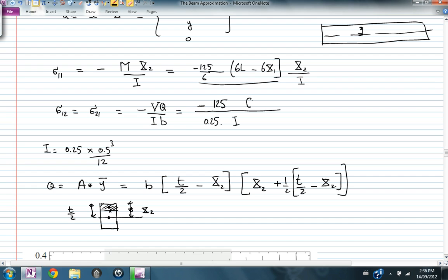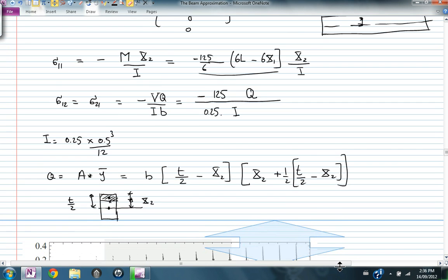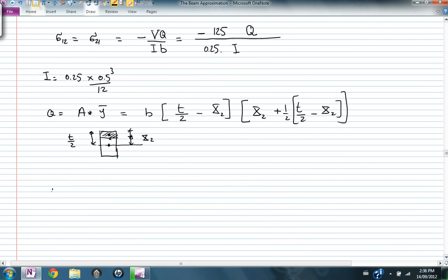And so you put Q here, and this gives you sigma 1, 2. So your stress at any point inside the beam is given by a matrix, because the stress, as we know, is a matrix of values, where you have a value of sigma 1, 1, you have a value for sigma 1, 2, you have a value for sigma 2, 1, and a non-zero value, and the rest is equal to 0. So these are the numbers. Now let's visualize the results.